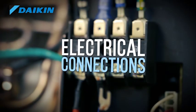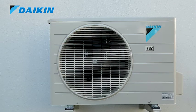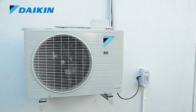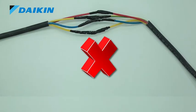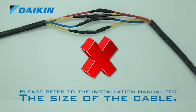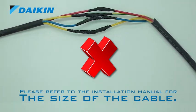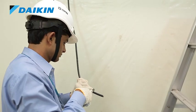Electrical connections. After installing and connecting indoor and outdoor units, we need to now do the electrical connections for them. For making electrical connections, make sure the main power supply is given at the outdoor unit only. In any case, main power supply must not be given at the indoor unit. Also, there should be absolutely no joints in the cable, as it may lead to fire, and size of the cable must be as per the specification mentioned in the installation manual. First, make the connections at the indoor unit.